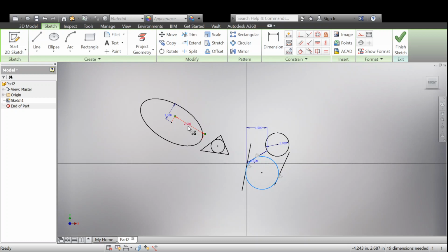So once you give something a dimension, you're not going to give it another one, you're just going to be able to alter it. You try to give it another dimension, it's going to say, error. There already is a dimension. You're over-constraining this sheet. You can't give another dimension to it. And it'll literally give you an error message when you try that.